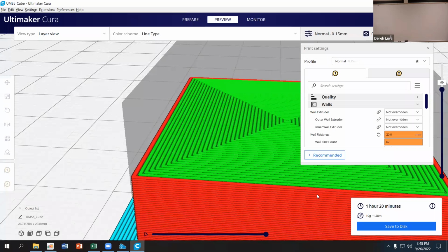Whereas the infill will help keep the layer on top of whatever you're building out smooth. So if you have a lot of void on the inside of your part, the infill is going to keep that void from flexing or deforming. And so it's going to keep that rigidity so you don't lose the shape of the object you're trying to print.